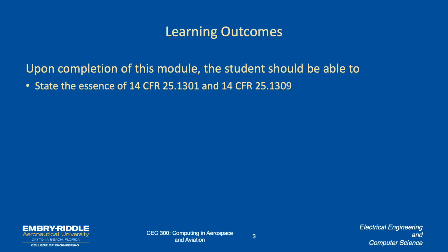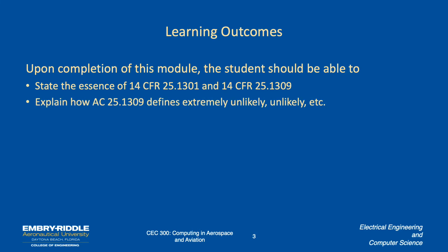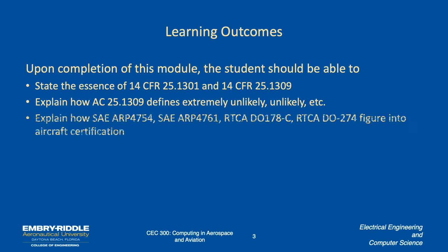When you get done with this module, you should be able to state the essence of 14 CFR 25.1301 and 25.1309, explain how advisory circular 25.1309 defines extremely unlikely, unlikely, etc., and explain how SAE ARP 4754, 4761, and RTCA DO-178C and DO-254 figure into aircraft certification.